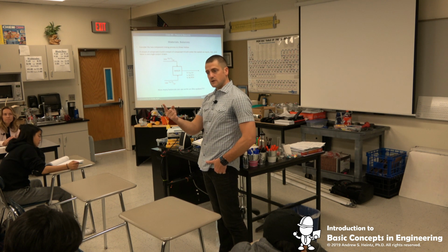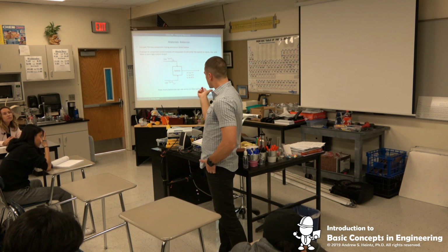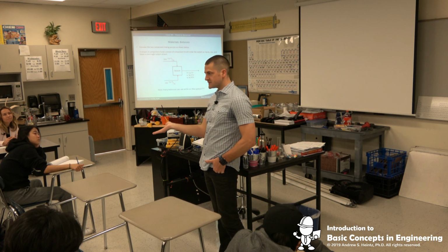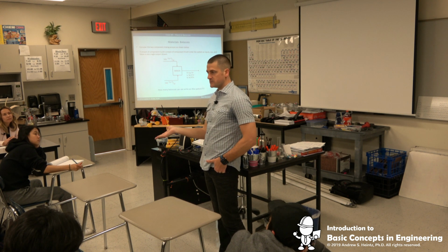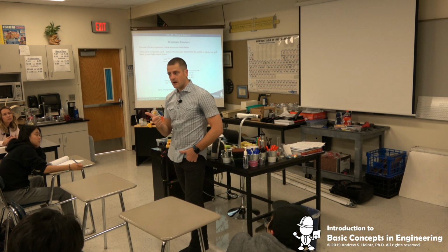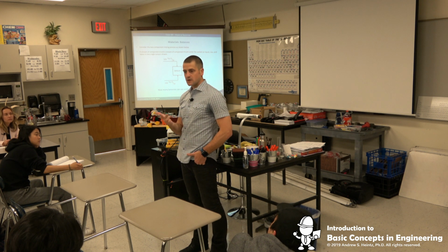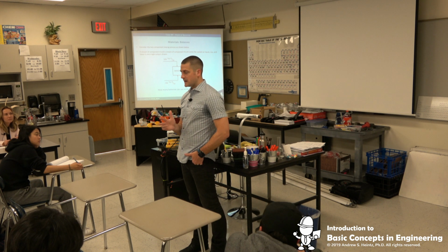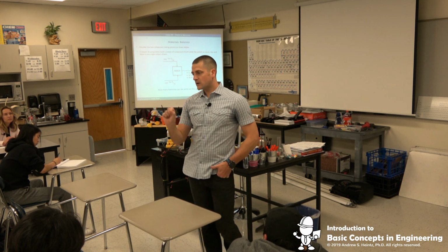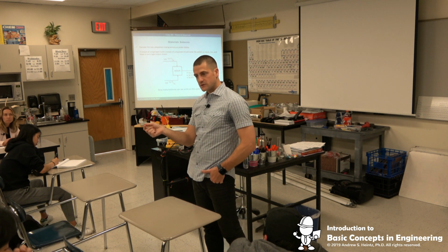So that's one equation. The second equation you had, in this case, is not really an equation. It's just A in equals A out, and B in equals B out. So what that gives us is three equations in this case. We have a total mass balance, a component A balance, and a component B balance, right? And again, in this case it's very simple, but what you can end up doing is using variables, or using one equation to plug into and solve for the other equation.